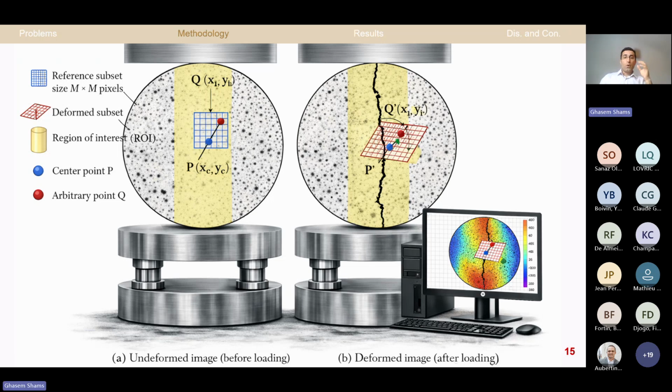So, while acoustic emission tells us when and how microcracks form internally from inside the specimen, DIC tells us where deformation localized on the surface of a specimen. Together, they allow us to link microscale cracking to macroscopic fracture and deformation.